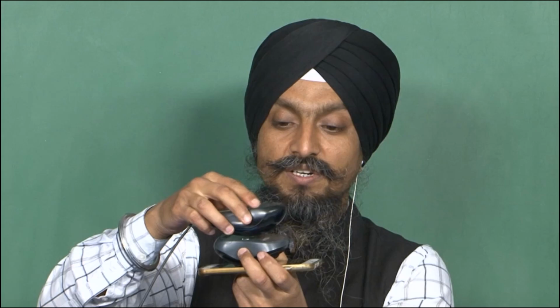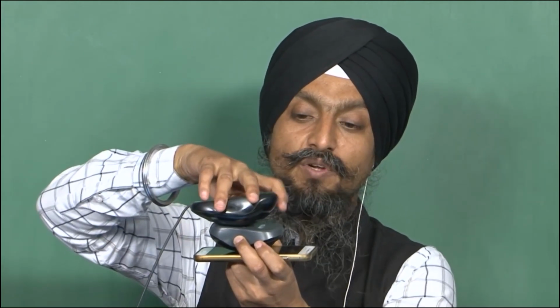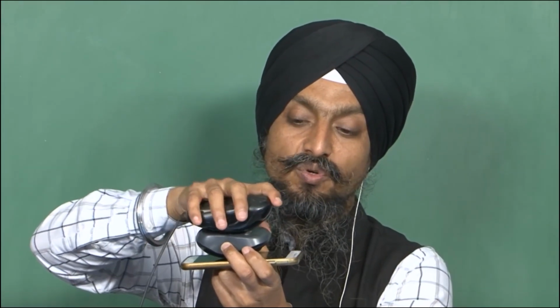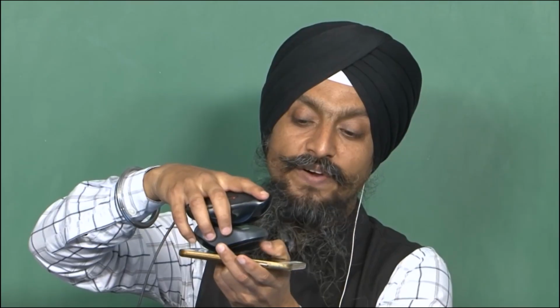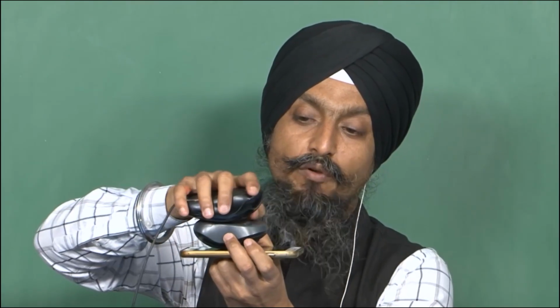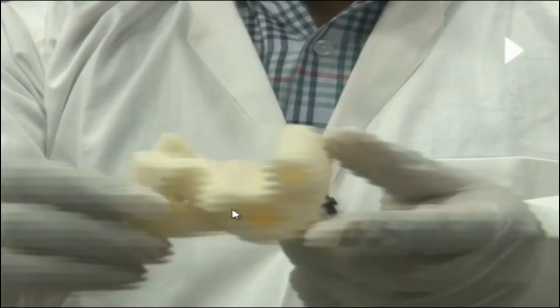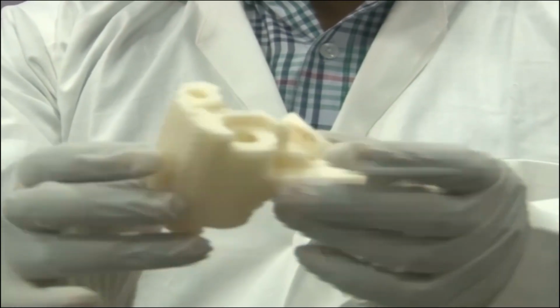For instance, this is the model, like I just said, it is touching the bed. If there is another thing manufactured here, the portion in between here is not touching the bed, but it would provide support here as well, because it has to produce this as well. So in case of touching bed, it will provide support here only. In case of everywhere, it will provide support here as well. So which is complicated, we use the option everywhere.